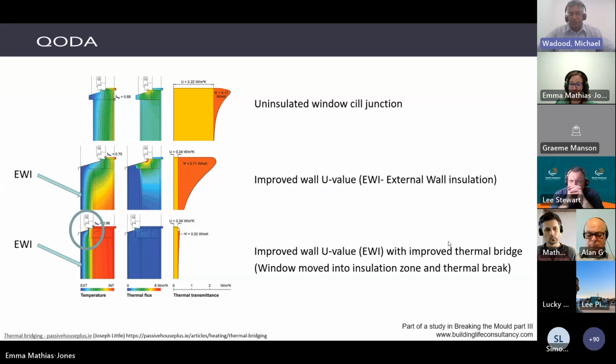So ideally, building control practitioners should be asking questions around thermal bridging within their plan assessment, and equally, architects should be questioning energy consultants like yourself about thermal bridging and areas of concern, and making sure that they're well detailed and incorporated within the overall thermal value calculation. Yeah, because they're becoming increasingly more of a concern, and as you can see, there's no point just focusing on improving the U values. You've got to look at both, otherwise there's very little improvement.